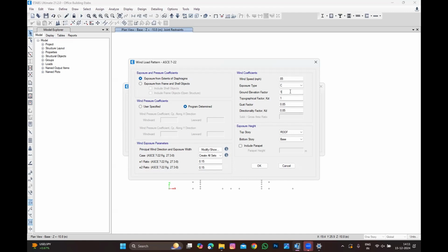Sir, I don't get any kind of scenarios, I'm building on top of liquefaction. You will never notice it unless the seismic comes. If the seismic comes, the shear velocity of the soil is too low. Immediately what will happen? It will collapse in a matter of seconds. That's what happened in Turkey. So many buildings, if you go and see the photos, without having any cracks, the building has toppled because of the liquefaction, because they did not test it.